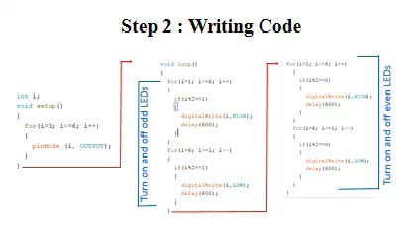Then the second loop runs from 6 to 1. If the variable I gets odd value, then the digital write function will send low voltage to the LEDs. So the LEDs that are now turned on will turn off in a reverse manner.